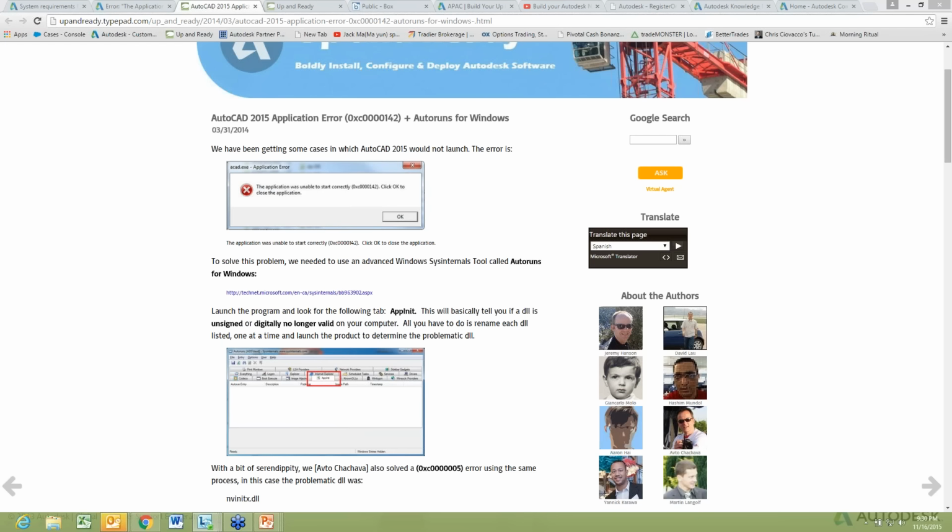Is there still an issue with path links on 2015 deployments? The answer is yes. It's actually a Windows path limit. It's not anything to do with our software specifically. Windows has a 256 character path length limit. So if some of the suites have very long paths in them, long file names, and if you're going to hit the 256 character limit, then absolutely.